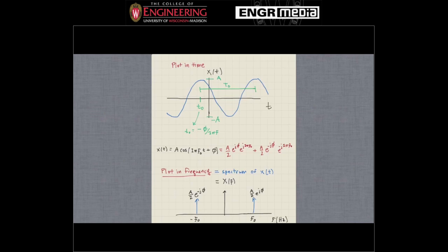So instead of this time-shifted sinusoid that I'm showing here, if we just plotted cosine of omega naught t, without a phase shift, we just try and draw that in. Okay, so what is the value of t naught? Well, it's actually written below here: t naught equals minus phi divided by 2 times pi times f, where f is the frequency of this sinusoid.